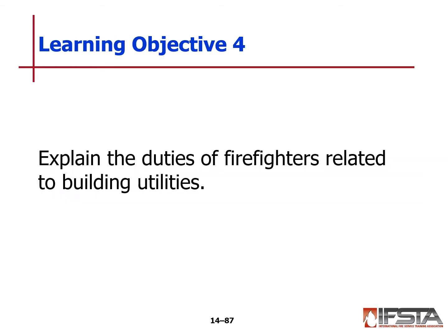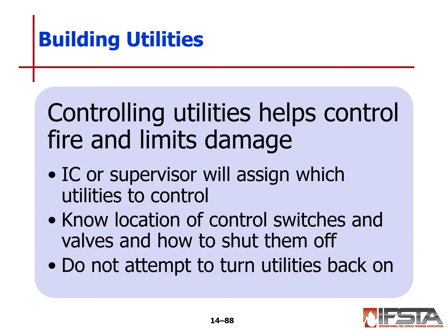Next, the duties of the firefighters that are related to building utilities. Controlling utilities helps us control the fire, and it can limit the damage. The incident commanders or the supervisors make the assignments which have us control these utilities. We need to know the location of control switches and/or valves and how to shut them off. We do not want to attempt to turn utilities back on. We let the proper utility company take care of that.